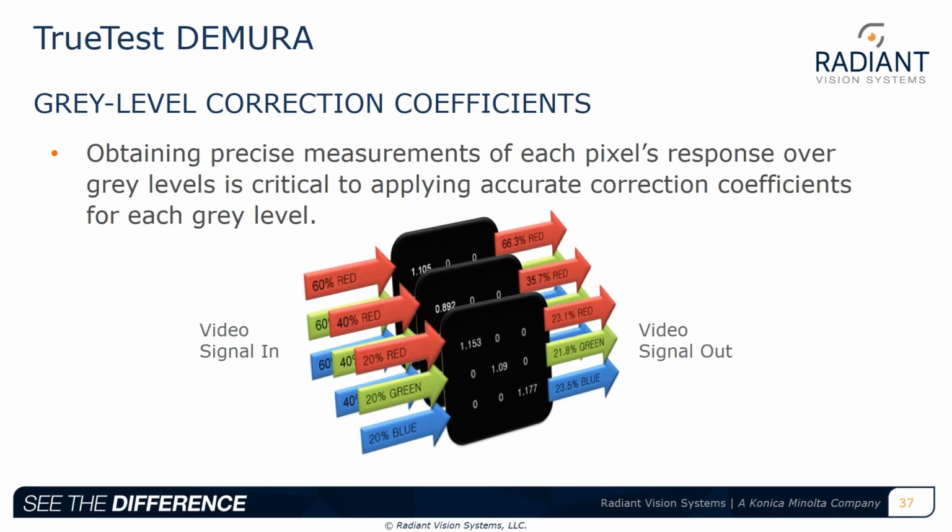An OLED display typically requires luminance-only correction. The 3 subpixels have a correction coefficient. A pixel has 3 correction coefficients, which in simple terms means that after a video input signal is given, an RGB signal of 20%, we simply scale the signal by a known value, and that is our correction coefficient.